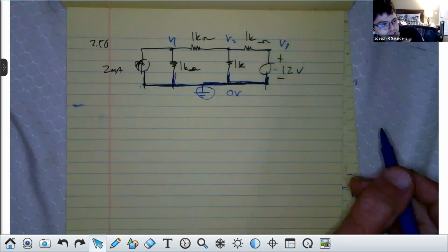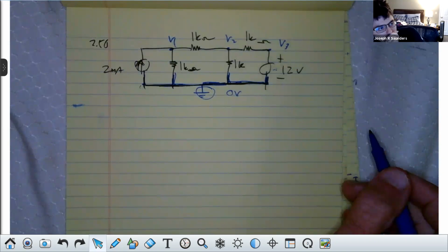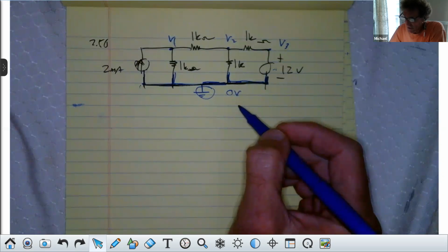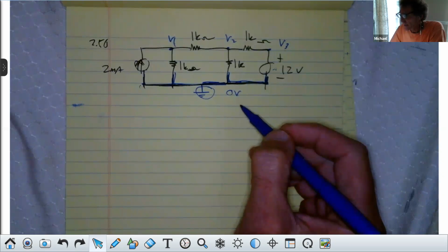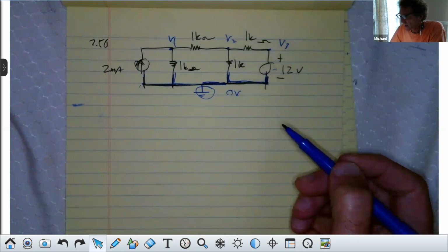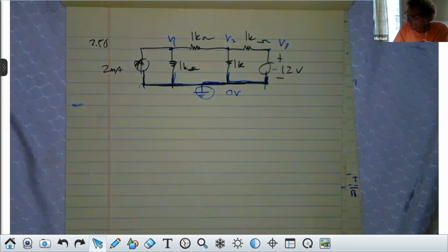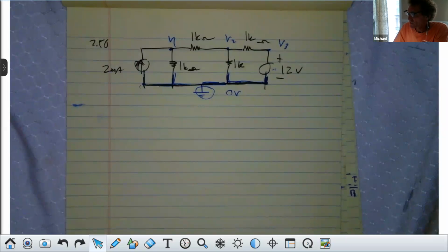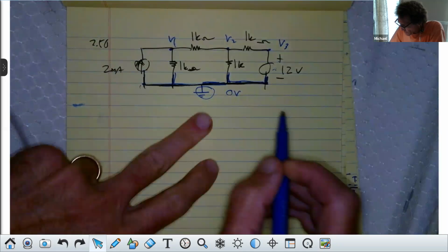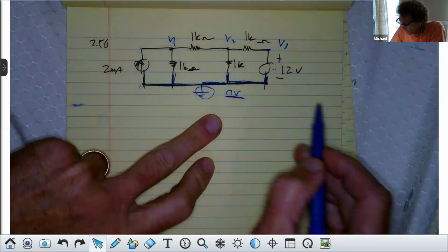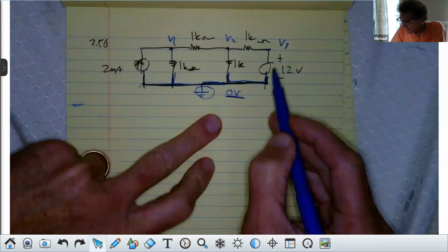Could you explain that? I didn't really follow grounding last time. Could you go over that? You know, voltage is like pressure, right? And pressure is always relative between 2 points. Pressure by itself means nothing unless it's measured with respect to something. If something is 30 pounds per square inch above a certain point, then you know that's the difference, and that difference will drive the flow of water or air. Correct, class? All right, if I'm calling this 0, and I call this V3, it means this point is going to be measured with respect to this being 0.